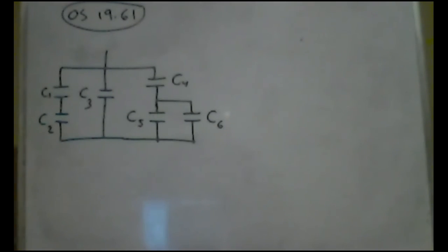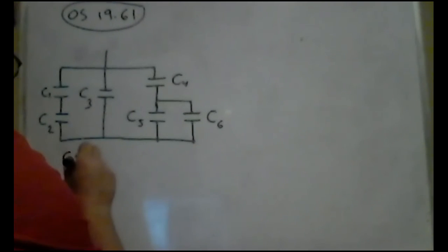So I have all these capacitors in this arrangement. Instead of this big arrangement, I'd like to have one capacitor that's equivalent to all of these. So how do I figure this out? It's a matter of looking at them, drawing equivalent diagrams, and whittling it down. First, I need to state what my actual values are. C1 is 5.0 microfarads.